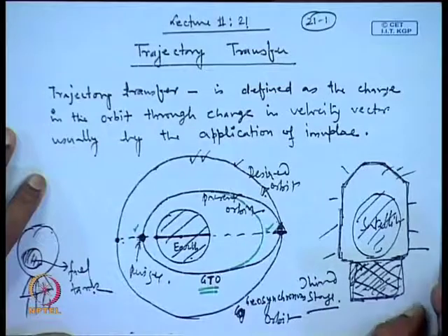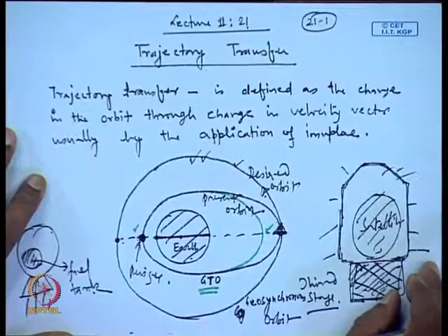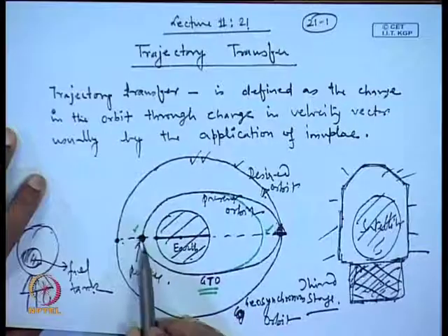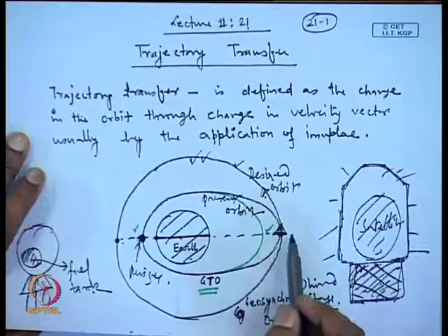So, various kinds of trajectory transfer, how to do it, when the energy involved is minimized, and sometimes maybe a small eccentricity you require while transferring. Various factors are there. In fact, sometimes you have to transfer it such that you catch a satellite in another orbit. That is called the chase maneuver.